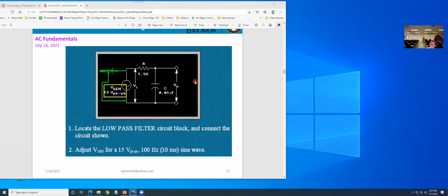How can you do? Check your source setting. You already know the source right here, already displayed on the oscilloscope. From the oscilloscope setup, you have to make sure you have your source set up for channel 2 if you're using channel 2.